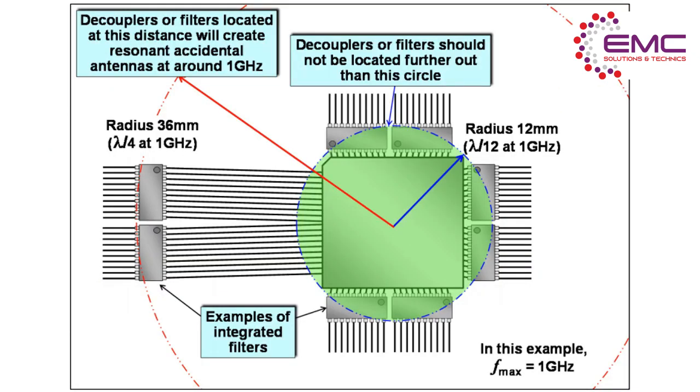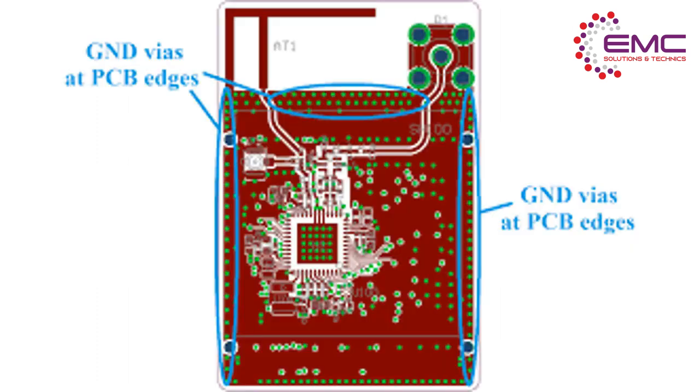Digital circuits. When dealing with digital circuits, extra attention must be given to clocks and other high-speed signals. Traces connecting such signals should be kept as short as possible and be adjacent to the ground plane to keep radiation and crosstalk under control. With such signals, engineers should avoid using vias or routing traces on the PCB edge or near connectors. These signals must also be kept away from the power plane, since they are capable of inducing noise on the power plane as well.